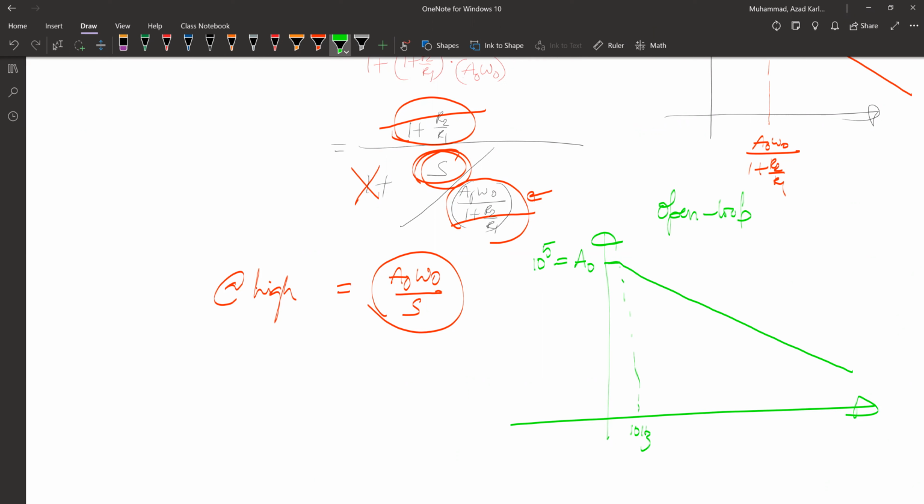And if you're trying to build a non-inverting amplifier configuration using this, which has a very small gain, say 1 over R2 or R, right? It so happens that at all the low frequencies, it behaves constant. And once it reaches this frequency, it just follows the open loop op amp's behavior.